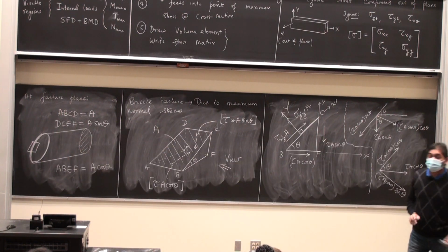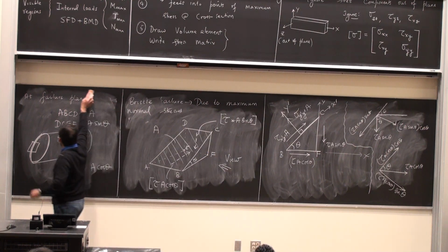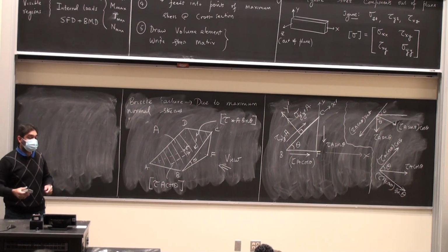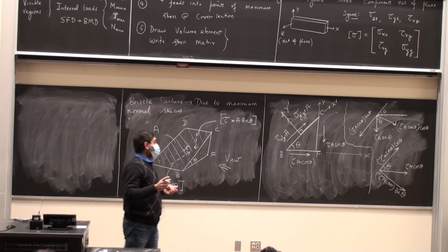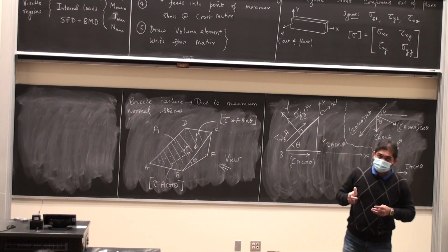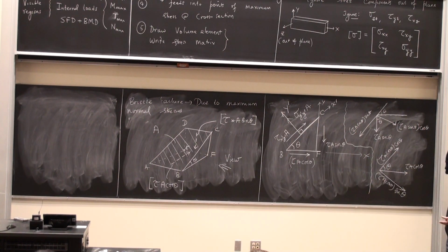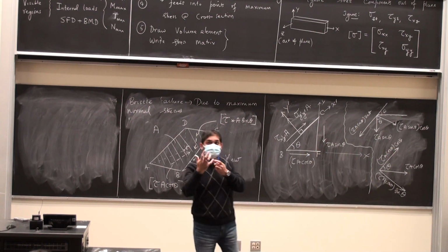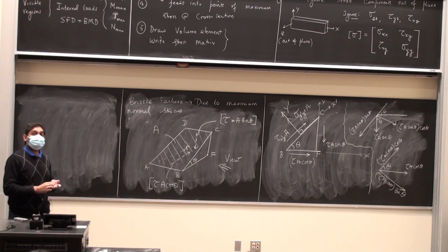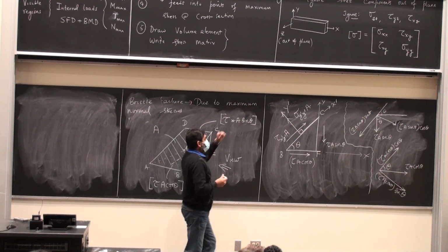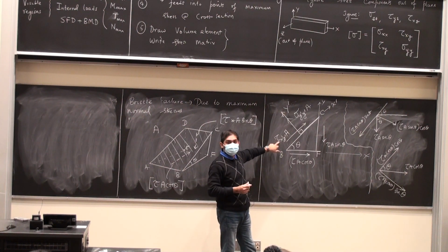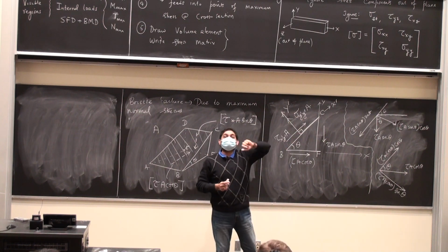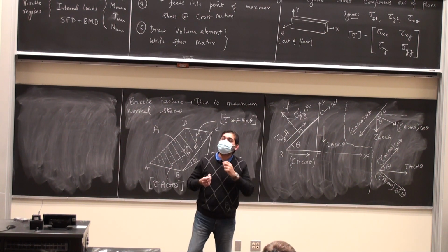Just hang on for a few more minutes and you'll see where we are going with this. Two things I mentioned. One thing, brittle material fails due to normal stresses. The other thing is that if I have the principal stresses, the maximum normal stresses, that principal stress will not have any shear stress on that particular plane. So what is going to happen is that this guy has to disappear and this has to become a maximum. Does that happen at the same angle is the question. And that's what we're going to figure out.